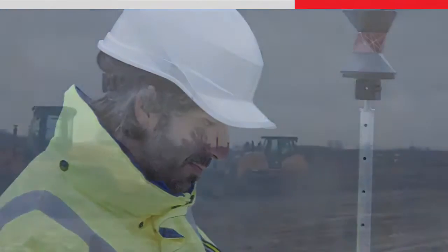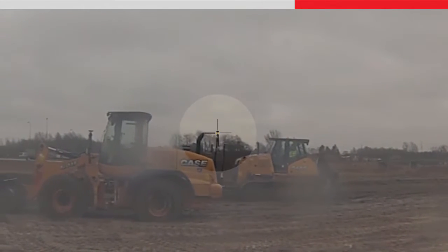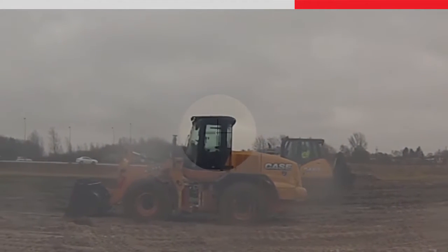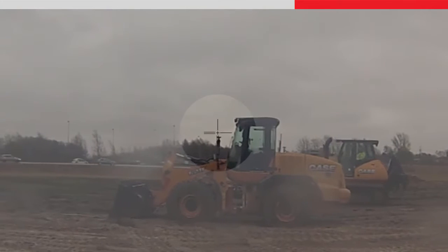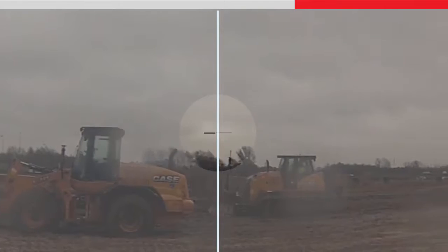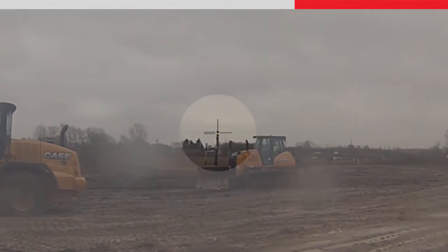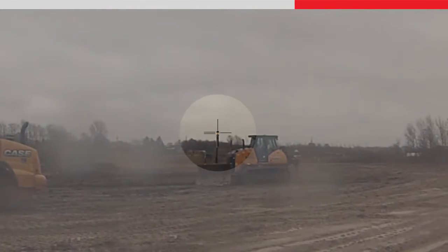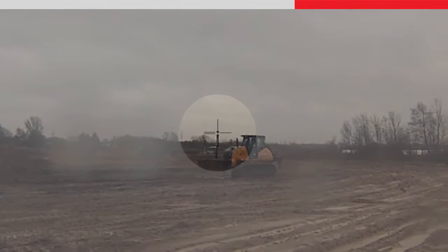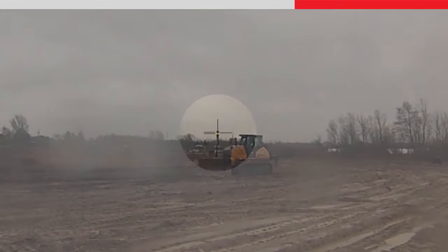Imagine now a MultiStation is being used for machine control and a target is being followed on a dozer. The dozer moves behind another machine and the instrument loses lock to the target. The dozer stops and drives back in the opposite direction. A cube search will start and the instrument will find and lock onto the target even with the dozer still moving. Again, this is a massive time saving because the dozer driver does not have to stop the machine and wait for the instrument to lock to the target.